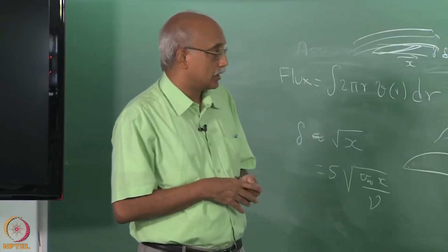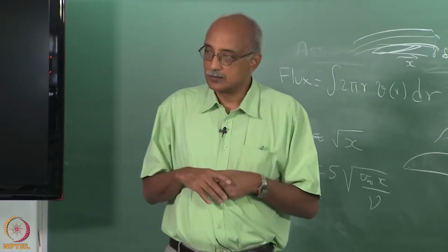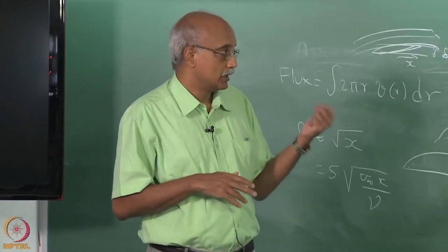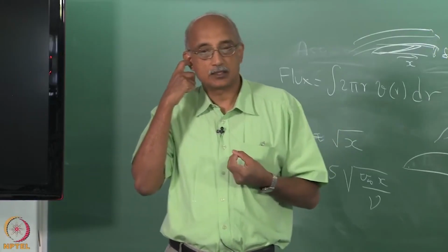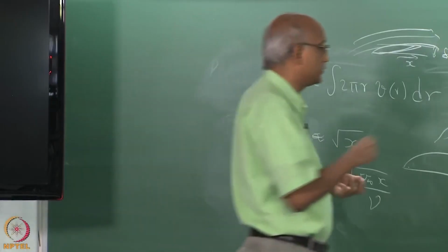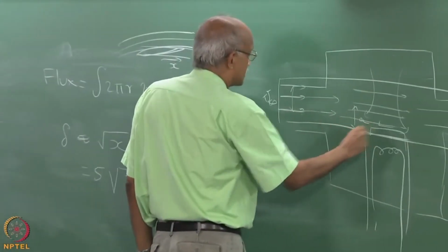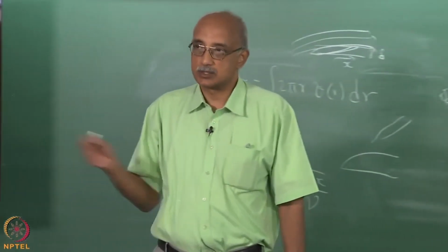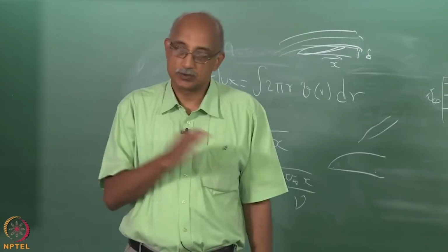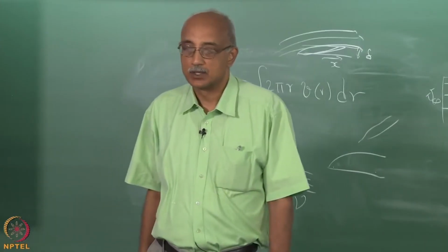And so, again, when you are designing the reactor, these kinds of correlations are very helpful in ensuring that you control the spacing between the inlet and the substrate in such a way that you ensure that the transition happens prior to the fluid encountering the substrate.